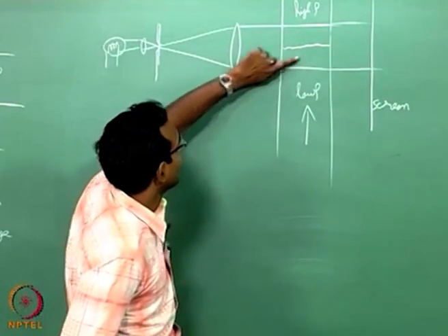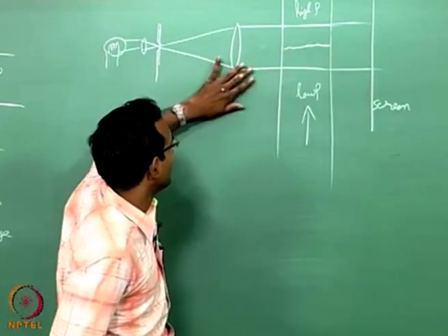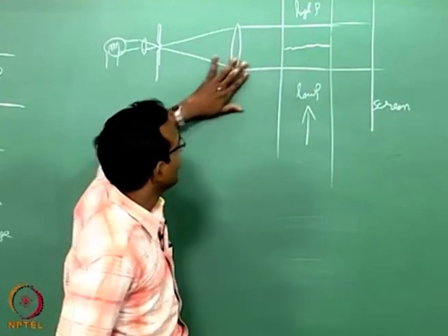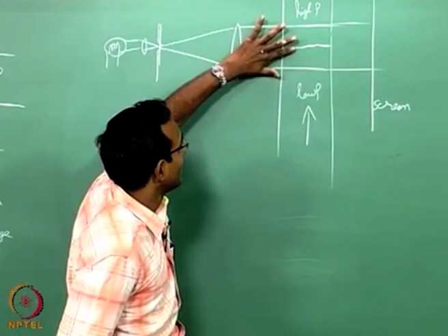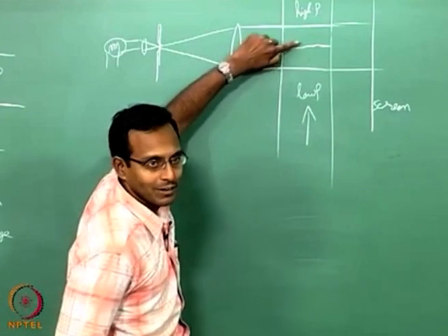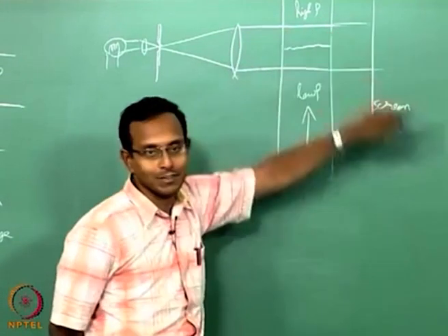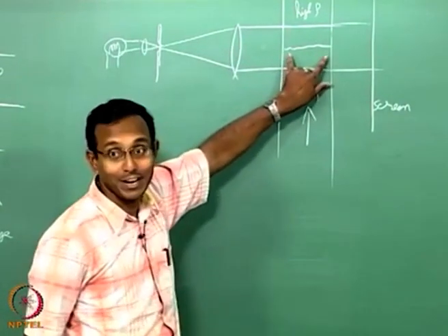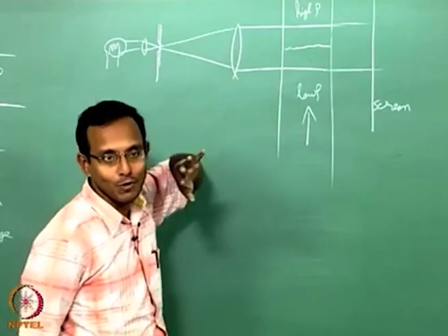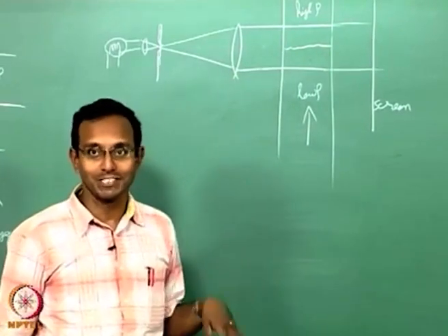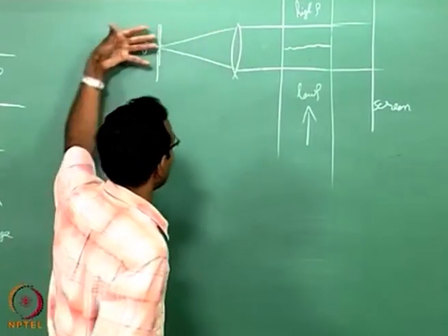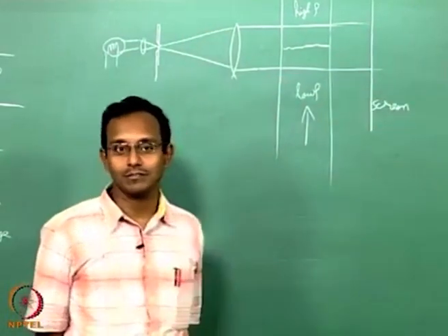This one here will refract, go out, no trouble, but there is a whole bunch of waves in the middle which will go refract, it will go hit this shock somewhere, turn more, and then go out somewhere else. The shock will be spread out more. If you want to get very thin shocks, which is what is reality, I have to take the experiment and do it straight this way, perpendicular. Okay.